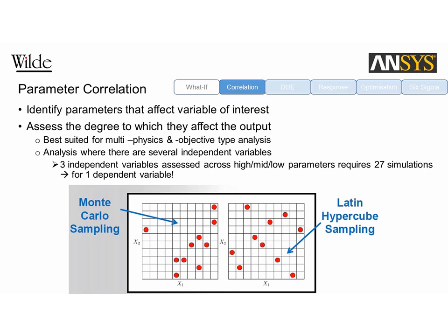The difference between Monte Carlo and Latin hypercube is that if you consider 2 input parameters, x2 and x1, in Monte Carlo, one of these parameters might be a repeating parameter. Although the design points themselves are different, each parameter might be repeated again. Also, there tends to be clustering of parameters. On the other hand, with Latin hypercube, you get a more even distribution throughout the design space. And what's more is that no value of the input parameter is repeated again. So it's a better use of computational resources, and at the same time, you're getting a broader understanding of the design space.